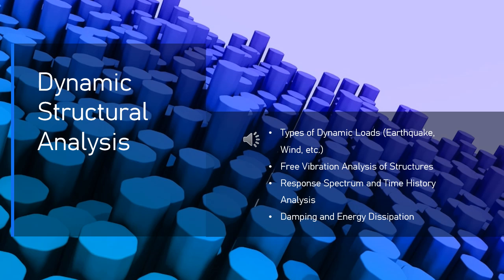Free vibration analysis is a fundamental part of dynamic structural analysis, providing insight into the natural frequencies and mode shapes of a structure. By understanding how structures vibrate naturally, engineers can design buildings, bridges, and other infrastructure to avoid resonance with dynamic loads such as wind, earthquakes, or machinery-induced vibrations. This analysis helps ensure that structures remain stable and safe under real-world conditions.